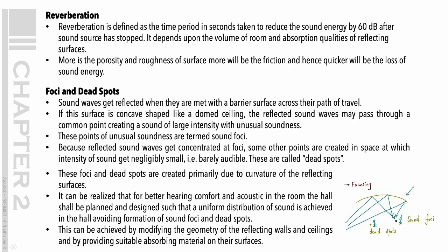Reverberation. Reverberation is defined as the time period in seconds taken to reduce the sound energy by 60 decibels after the sound source has stopped. It depends upon the volume of the room and the absorption qualities of reflecting surfaces. The more the porosity and roughness of the surface, the more the friction, and hence the quicker the loss of sound energy.